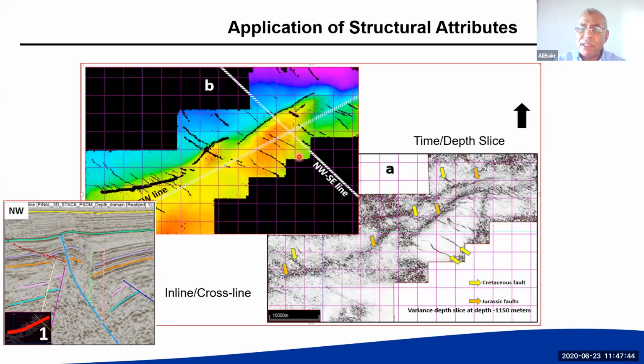I finish this segment and use my automated interpretation tools to fill in and check back until I finish all block by block, and then all my horizons would be interpreted. So my horizons have been interpreted in 3D vision, and my faults are also interpreted in 3D vision. I have the horizons and I have my fault planes together, so I can go directly and put them into a structural model. Now my horizons are okay and have been checked, and their termination against my fault planes has been checked. With both of them, I can start to build my structural model.